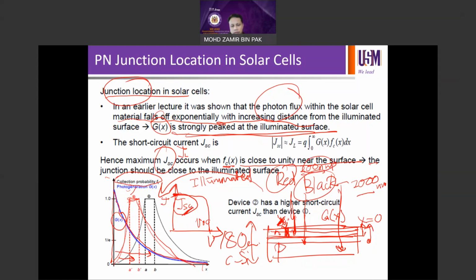surface, right? On the other hand, if you go for a very deep junction, then you should expect your carrier collection probability to be very poor because you're essentially bringing that curve into the device, and you should expect the fall off to reach zero before it reaches the surface. So therefore, the collection probability is not ensured, right?